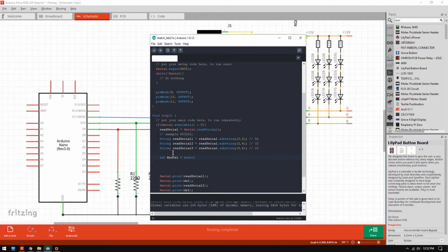Yeah, if this is a C function, we can search read serial 1. We're gonna take D6 here, and then this is null terminated, and the format data is 16 because the hex that we take is in 16-digit format.